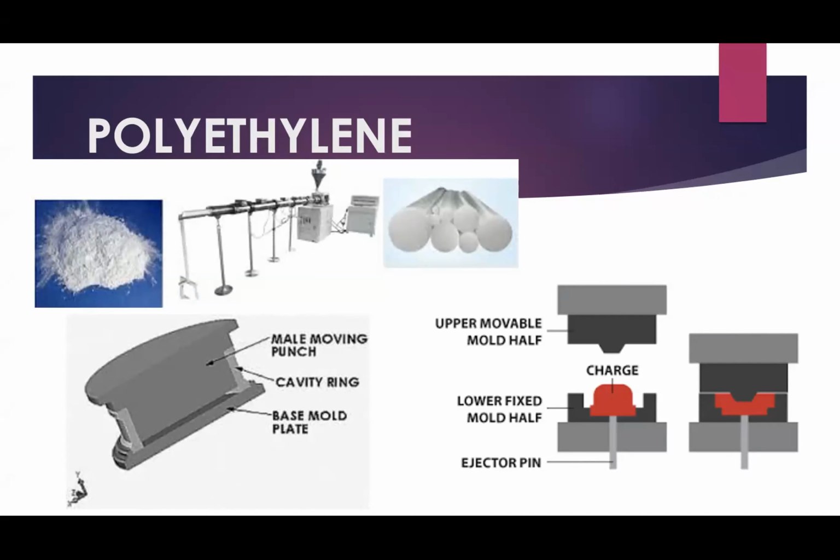And there are 5 stages of manufacture that you need to know for the exam. So the first one is polymerization, which can be 2 types, addition or condensation polymerization. So addition is where you basically add a free radical to the monomer with a double carbon bond.